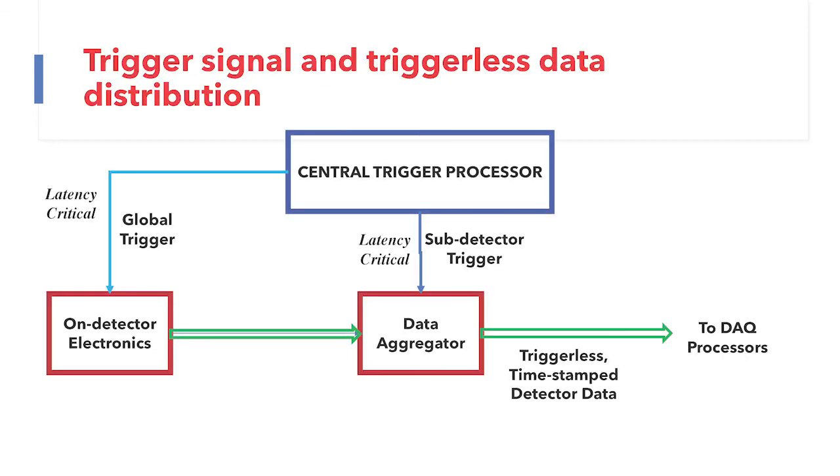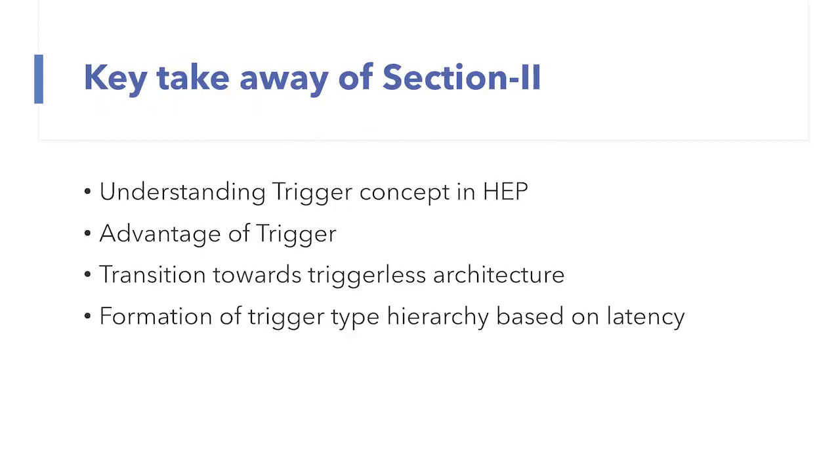In this part, I actually missed one point: different detectors have different latencies, and the important information for electronics and computer scientists is that these signals are latency critical. This latency cannot vary every time you reset, do a power cycle, or upgrade the firmware. So these are all latency critical lines. Okay.